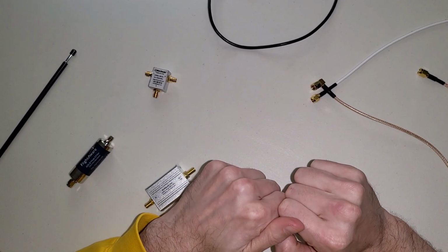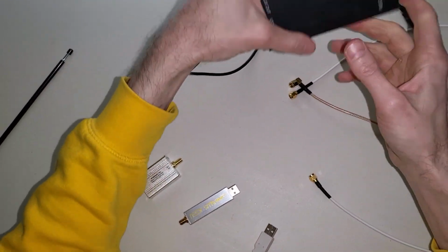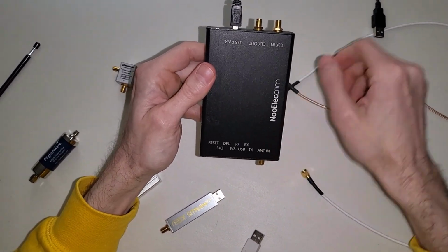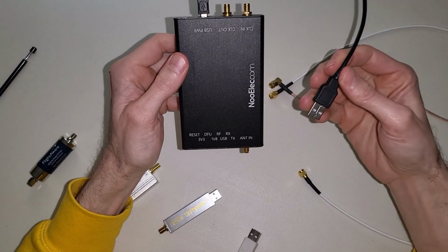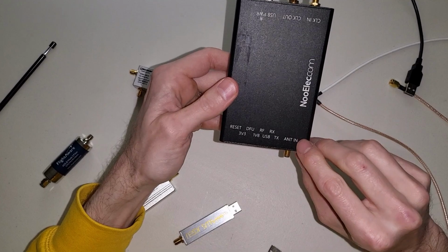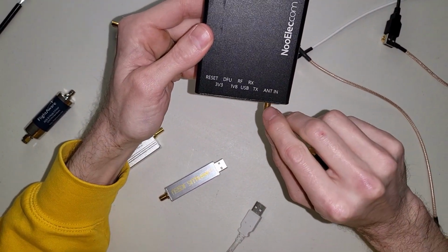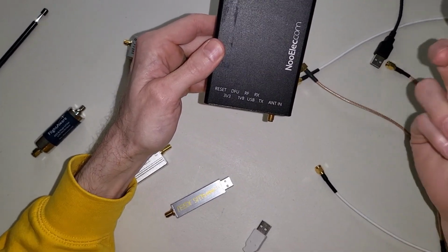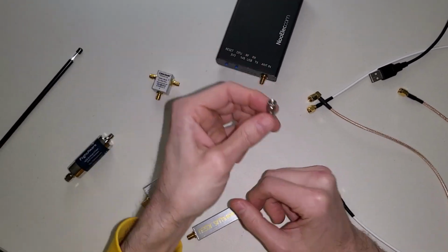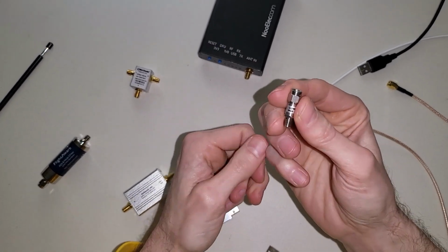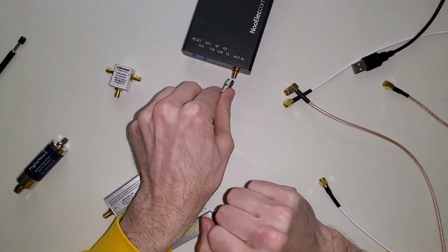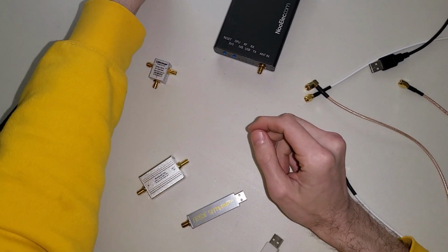Now, for transmitting, we're going to use a particular software-defined radio called a HackRF. This connects to the laptop using USB. And now the signals generated by this device are going to be quite a bit stronger than the signals we receive over the air. So we're going to attenuate the signals using a device called an attenuator. This is just a 30 dB attenuator that will connect directly to the ANT port on the HackRF.